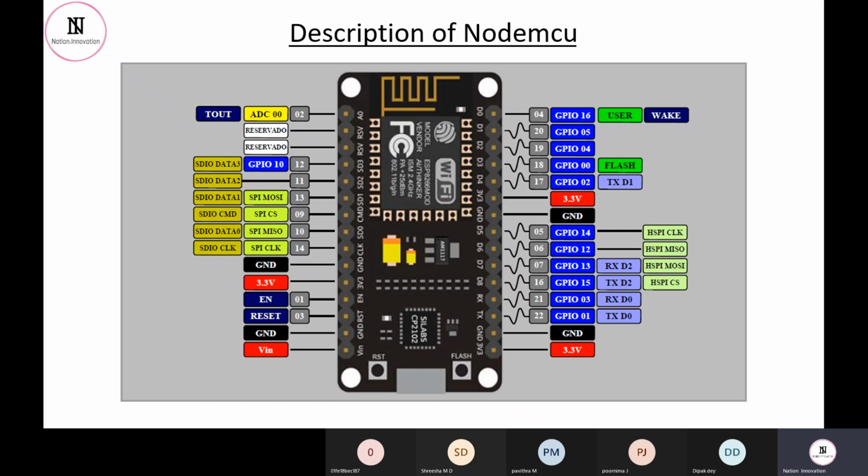Yes, we can consider it, because we do not have that much flexibility in providing power to the NodeMCU. Whenever you provide the power supply from the USB, it's perfectly fine, because the USB gives 5 volts, which is directly supplied to your AMS1117 voltage regulator, which drops that voltage to 3.3 volts. So it's perfectly fine. Just make sure that whenever we use the VIN pin, nothing more than 5 volts is supplied to the NodeMCU.